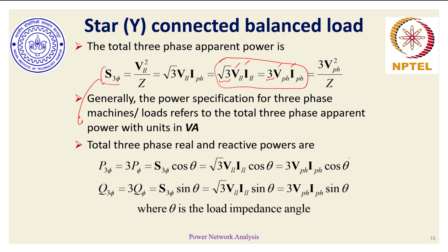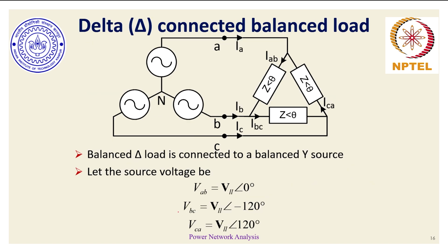If we take the corresponding real part of apparent power or complex power, that would give us the real power, and correspondingly the imaginary part would give us the notion of reactive power, where theta is the corresponding power factor angle or load impedance angle.